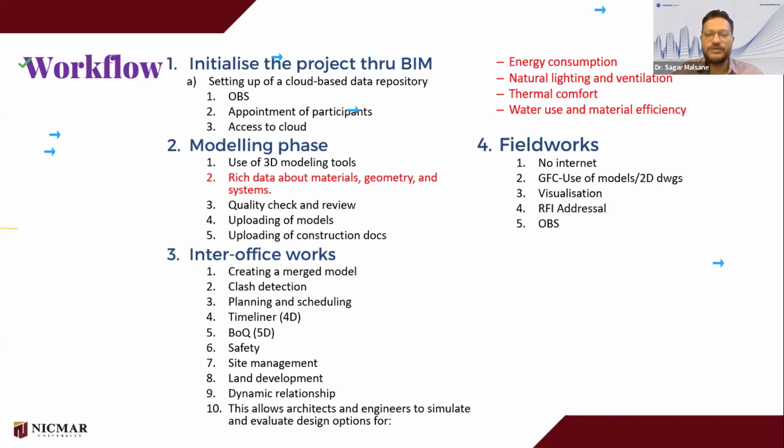So in inter-office work, it is expected that the models which have been created at the modeling phase will be used for energy consumption, understanding natural lighting and ventilation, thermal comfort, utilization of water and material efficiency. All those kinds of simulation and analysis need to be done before execution, so that this really helps towards achieving your sustainability related goal.